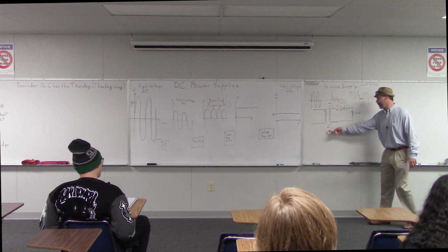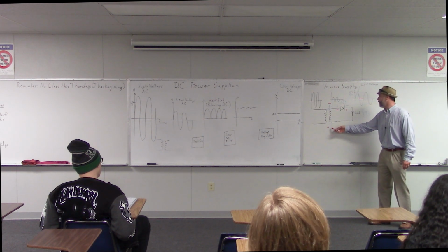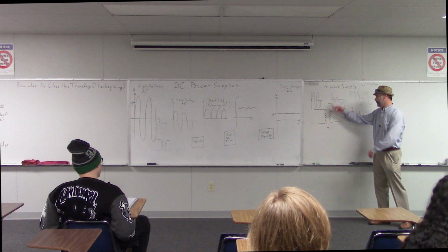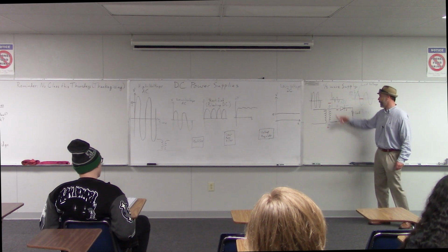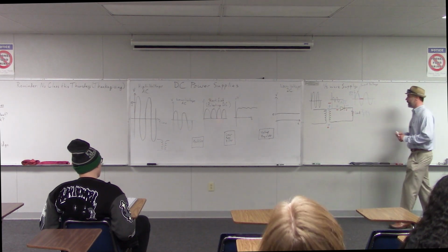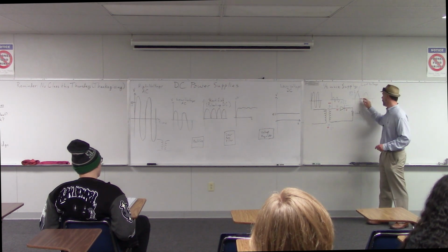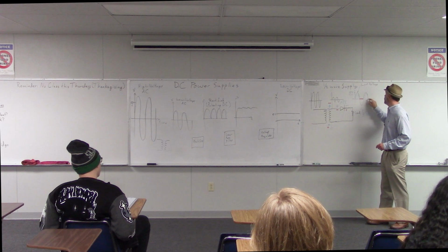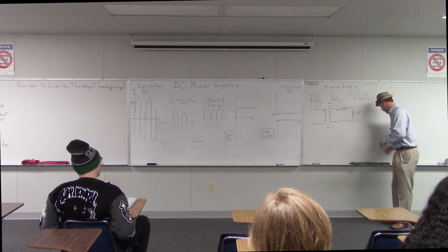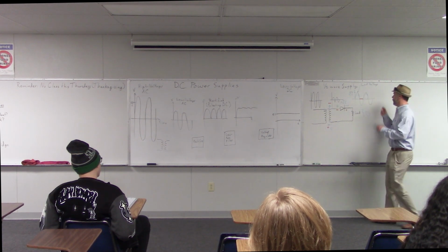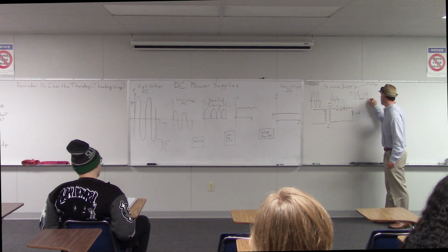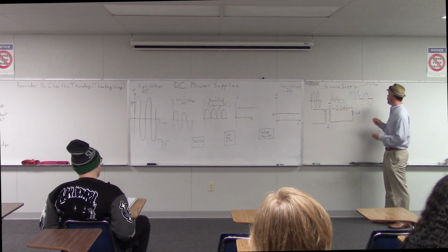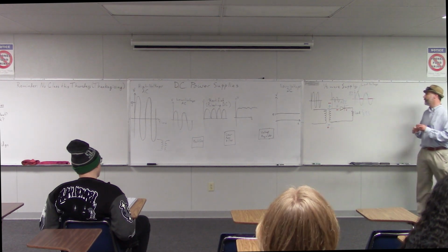So that would happen when we have a positive voltage down here. And then pretty soon, since this is an AC signal, the voltage would change again. We'd get the positive voltage on the top again. So then our signal would go like that again. And then when the input switches negative again, we get this 0 volt output. Okay?